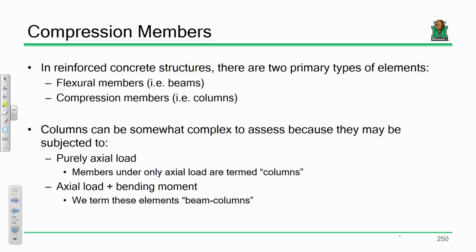What's desirable? Tension-controlled or compression-controlled? Tension. Why? It's more predictable. Well, I don't know about predictable. I wouldn't use that word. In other words, a mechanical way to describe what you're talking about is that a tension-controlled beam is more what? I'm talking about a mechanical property. How about the word ductility?